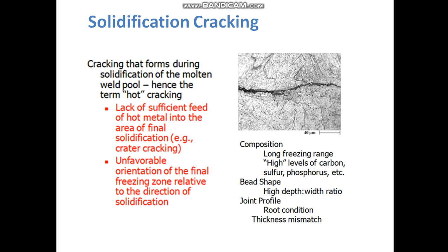The second phenomenon is solidification cracking. As you can see in the pictures, it is a crack that forms during the solidification of the molten weld pool. It is also known as hot cracking, because it forms immediately after the welding is completed, sometimes during the root pass or during the hot passes or subsequent filling passes. There is a lack of sufficient feed of hot material into the area of final solidification, the crater cracking.